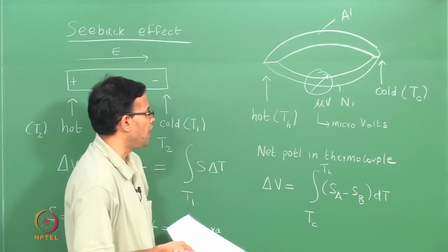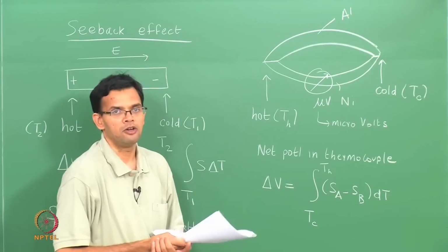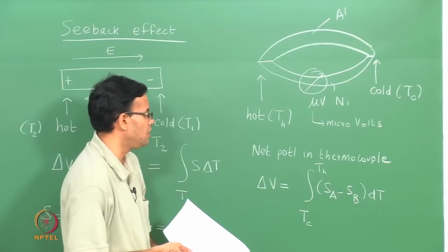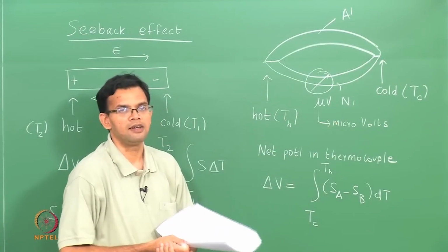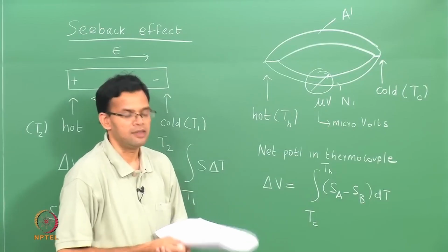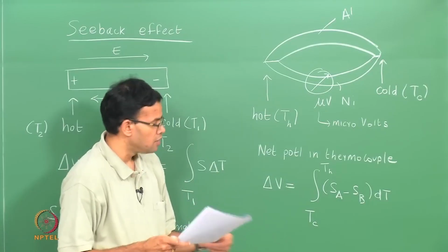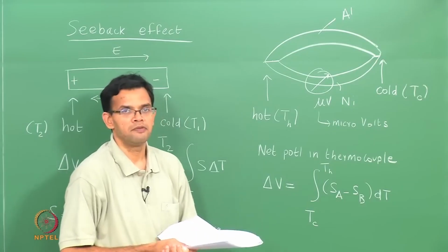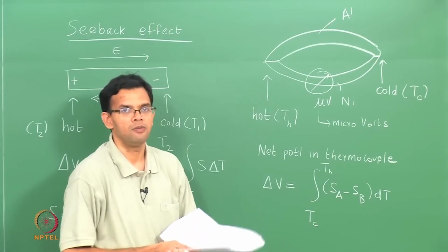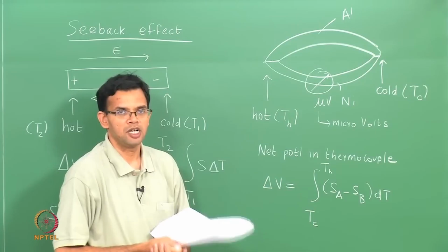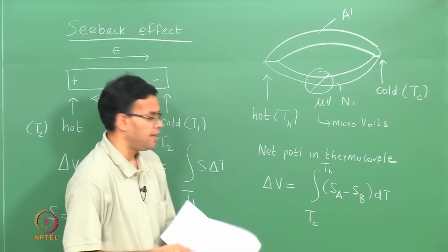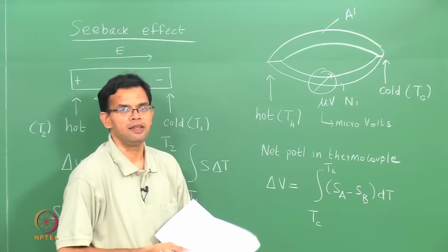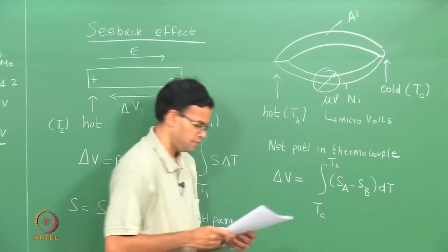So, if you want to find out the temperature of an unknown furnace or an unknown sample, by measuring the potential and then using standard tables, we can calculate the temperature. This is an example where metal-metal junctions are formed, and whenever you have these junctions, there will always be a contact potential. Next, let us move to a metal semiconductor junction.